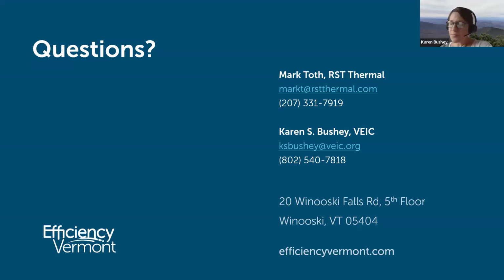Yeah, exhaust-only ventilation. We talked about that in other presentations we've done, where the problem is you don't know where the air is coming from. And a lot of times the air is coming from a basement or a garage. And a lot of times exhaust-only ventilation can make the air quality in the living space of the house worse by bringing more radon upstairs than we had. More chemicals that we store in the garage and basement are now being dragged through the house. So it's an interesting subject of monitoring and how to monitor it.